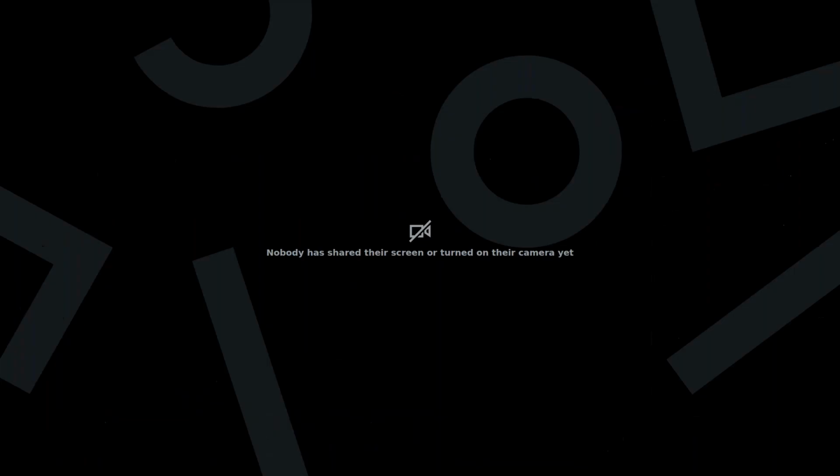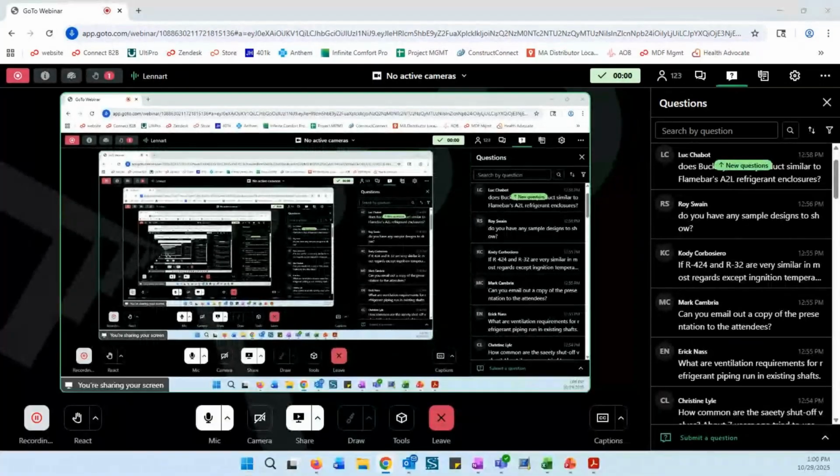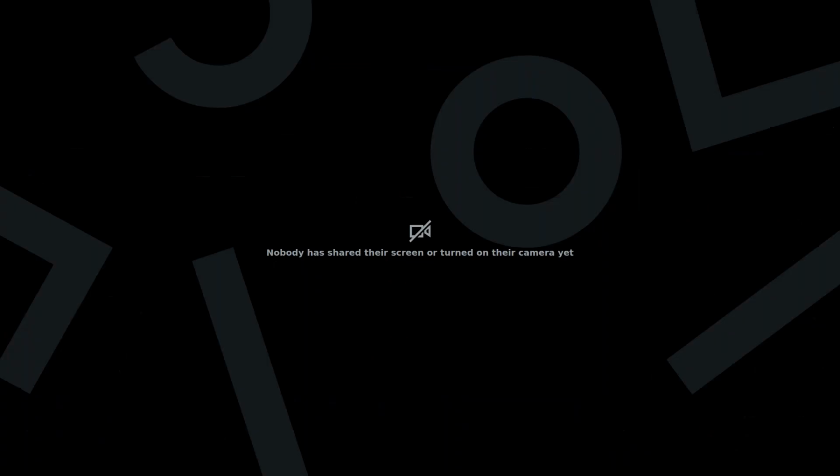Well, we don't see your roadmap yet, but Lennart, do you have anything to add to that about R454B versus R32? I can. I gave a webinar about that a year ago or so, but Fujitsu picked R32 because we have a lot of experience with that outside the US. We had it for almost 10 years. And you will see that now in availability and pricing also, but it's a few percent more efficient than 454B. That's the most common right now. It's also going to be less refrigerant charge in the system if you have R32.